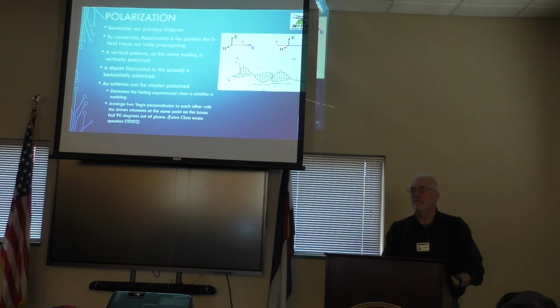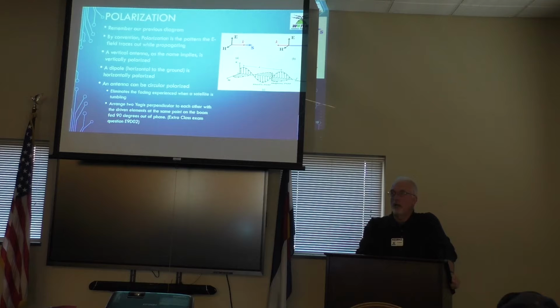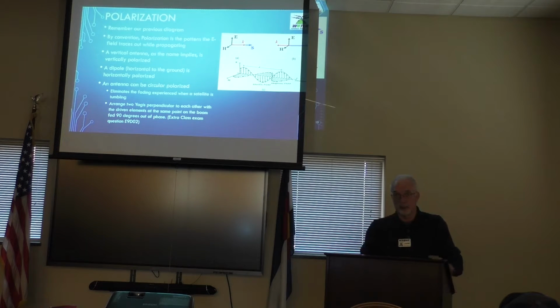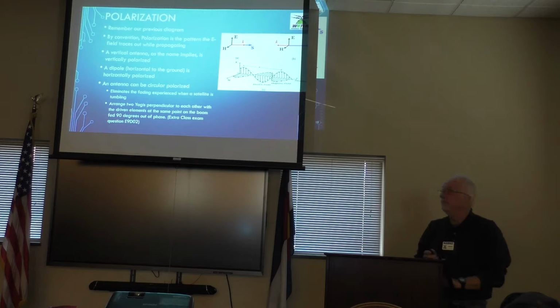Yes? So how is that phase shift achieved? Is it by placement of the elements or efficiency? That's a great question, because we're going to talk about that explicitly coming up. It's a phase shift in the feed line. So you're feeding one element, and there's actually a feed line a quarter wavelength long at the frequency that is creating that 90-degree phase shift. And I can show you how that works on a chart that's coming up.